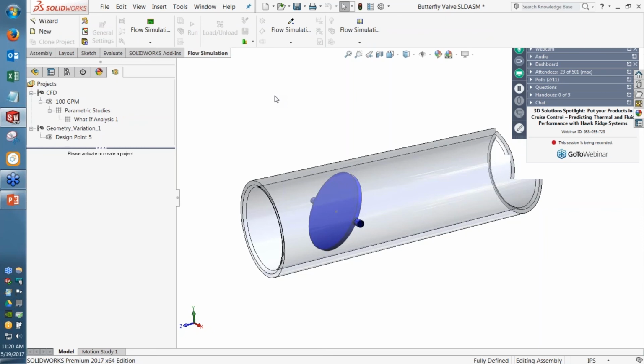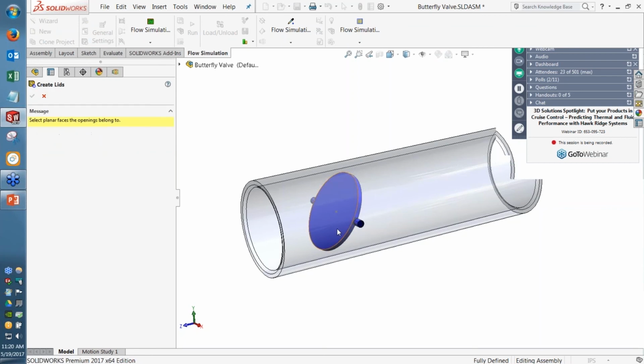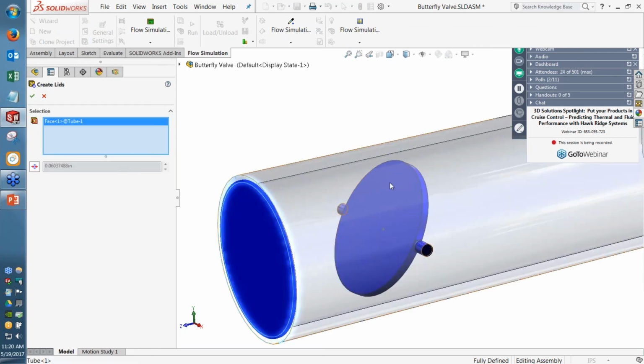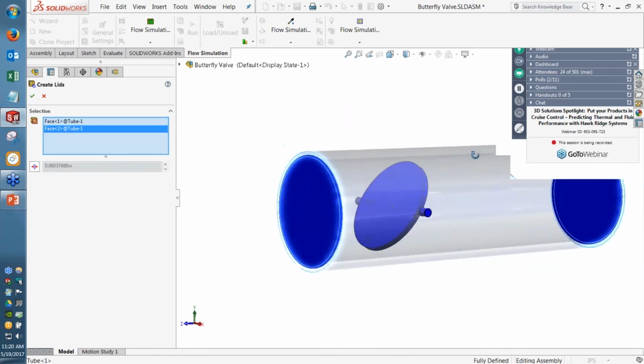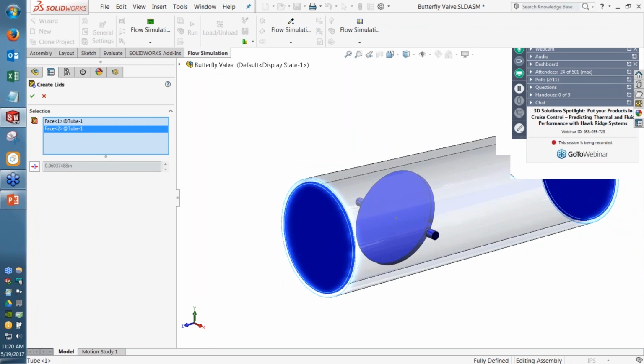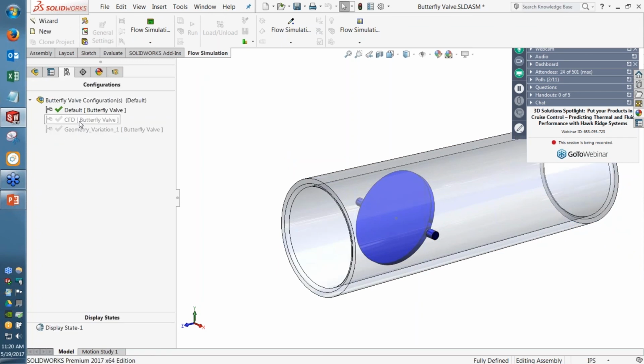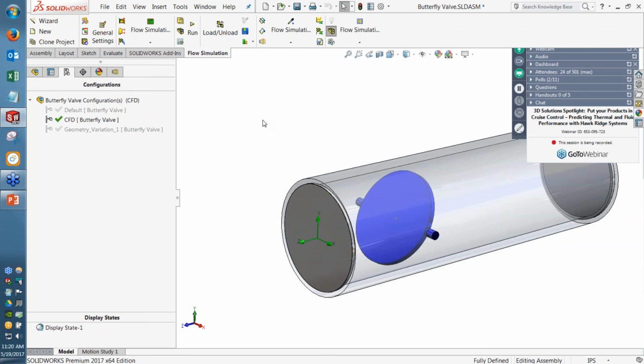First of all, let's go back and try to evaluate the valve performance and look at what the pressures inside this unit might be at if we are, for example, simulating water. So I can turn off motion and go enable SOLIDWORKS Flow Simulation instead from the same add-ins menu. So here again, I've just got my valve in sort of an initial arbitrary position, and maybe one version of this valve is going to be mechanically controlled. And so if that's, for example, the starting position that it's in, and I want to simulate that with SOLIDWORKS Flow Simulation, all I really need to do in this case, since it's going to be an internal fluid analysis, is to close up the openings in the model.